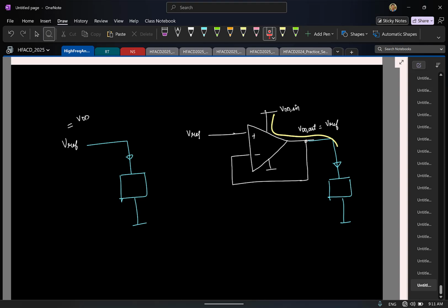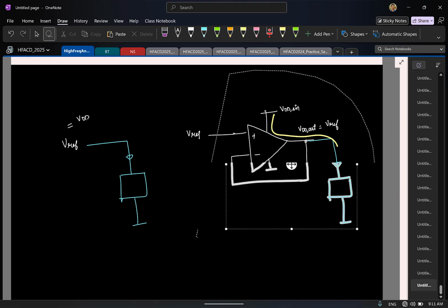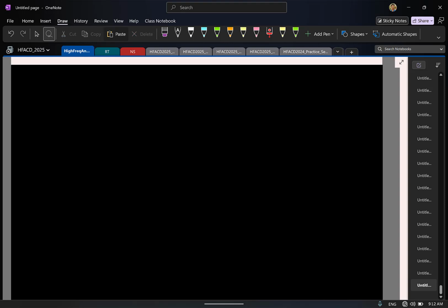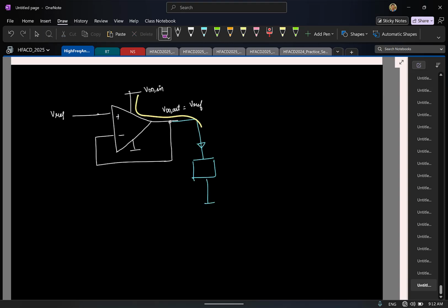Okay, so this works, but let me take it to next page. Okay, so this works, but one minor issue in practice. So once again, now this is an op amp which takes in 2 inputs, 1 output. You will realize it using a 5T OTA. But again, the moment your circuit here starts to draw a lot of current, it is as though you are connecting a small resistive load to the output, correct?